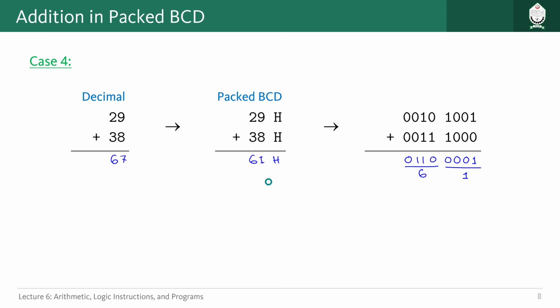So here how we are going to understand what to add, whether 06 or 60. Because if you remember, there was a carry from the 4th bit to 5th bit, or there was an auxiliary carry, right? In this particular addition, it will indicate we have to solve for the lower byte here.